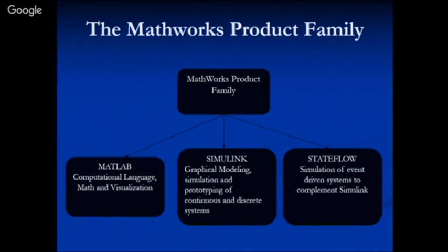Whenever you have a motor or a plant or anything, doing an analysis with the transfer function is very difficult, because in the transfer function model all the initial conditions are kept as 0. And only for linear time invariant systems can you use the Laplace transfer function model. But the state space model can be used for variable systems and MIMO systems, multiple input multiple output systems, and intermediate analysis is also done. A number of models are possible. We'll be seeing that also.